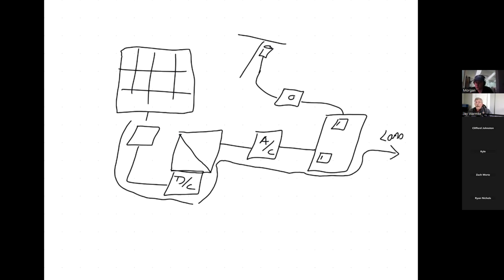So the power from your array is the most localized source of power, and it's going to go to your load. And then if you have extra capacity, if you're generating more power than you need, the grid now becomes a load, and the power is going to flow out onto the grid. All that that's doing is flowing. Think of it like filling a lower place. When water flows into an area, it goes to the lowest place first until that place is filled up level with the water, and then it goes to the next lowest, and eventually the whole load sort of spreads out. So the water reaches its level.